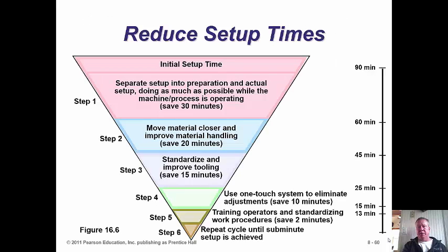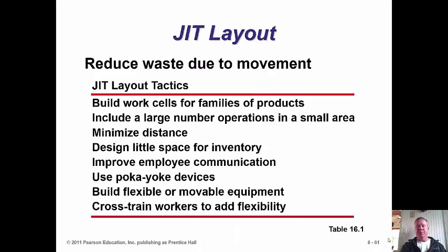Reducing setup times. This is their graphic for that, but anyway, the deal is, reduce those as much as possible, and it has to do with evaluating the process and finding out what's causing the excessive setup times. Just-in-time layout tactics, little inventory space, poka-yoke. Remember that poka-yoke are things that only go together one way.